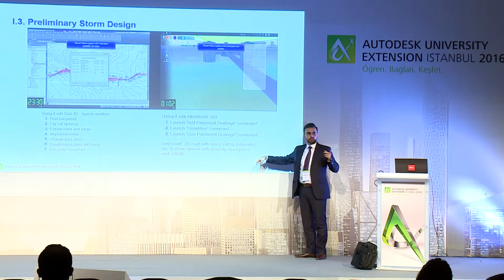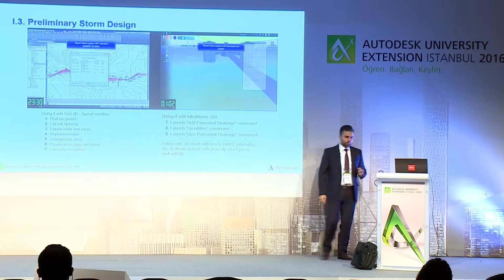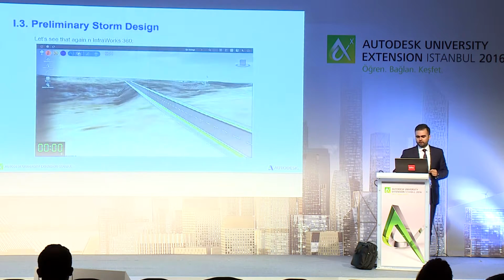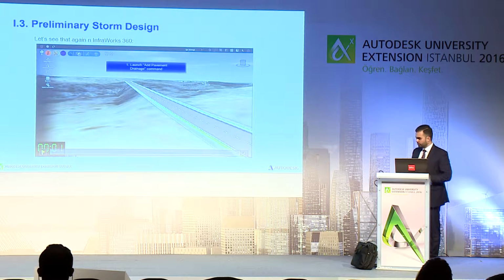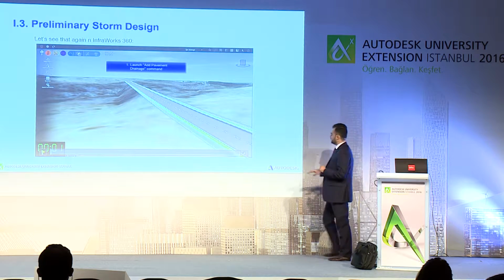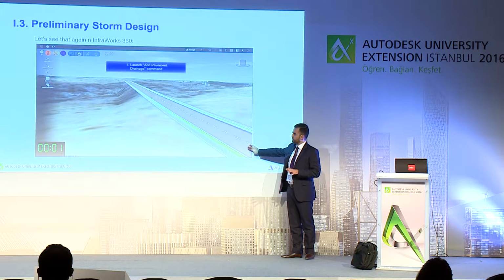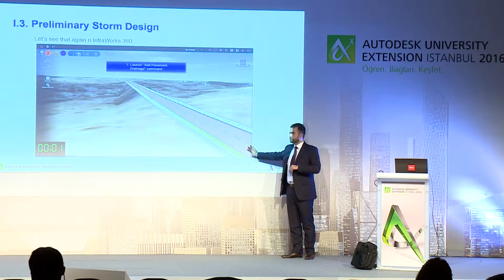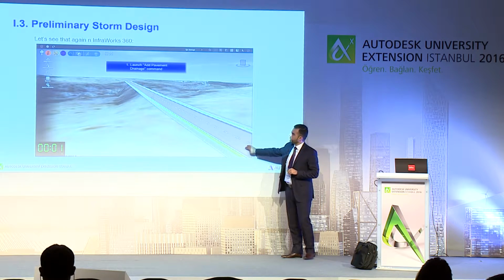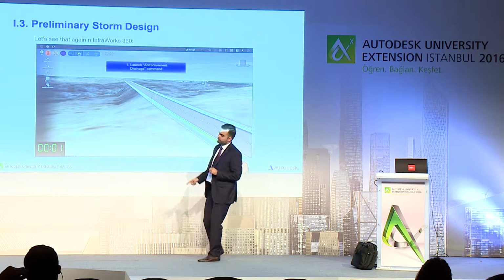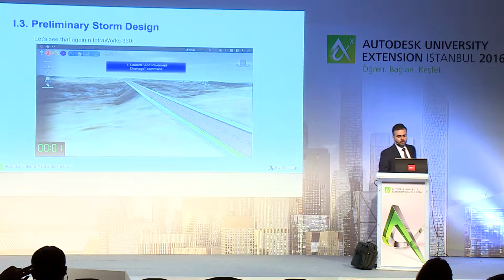And this is also making use of the power of the cloud. Let me pull into the original video. So what I'm doing here, we have a road that we have sketched as per the standard, or we brought in from Civil 3D. All I have to do is make use of, let me show you with the mouse, the drainage module.